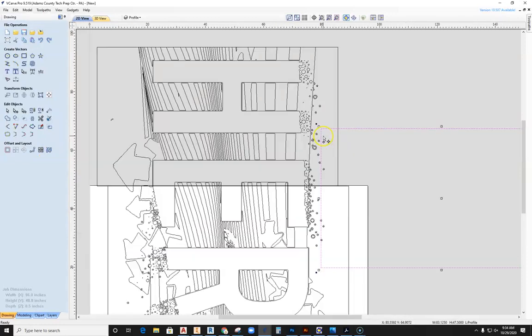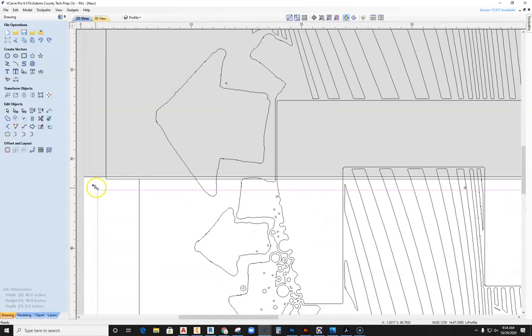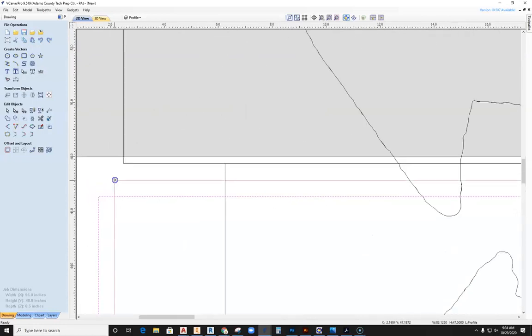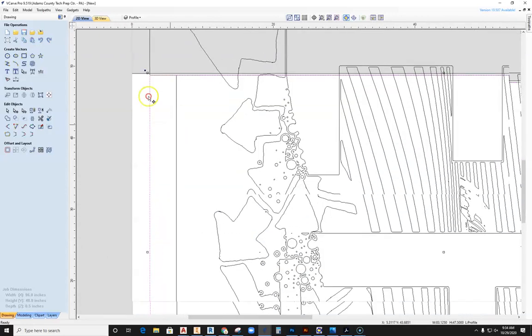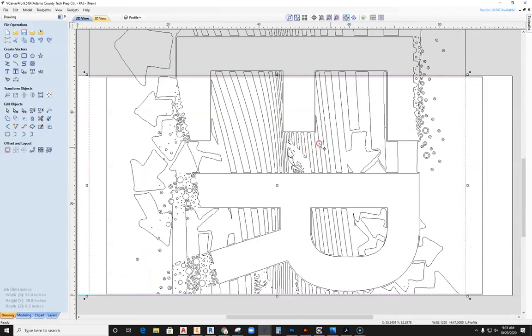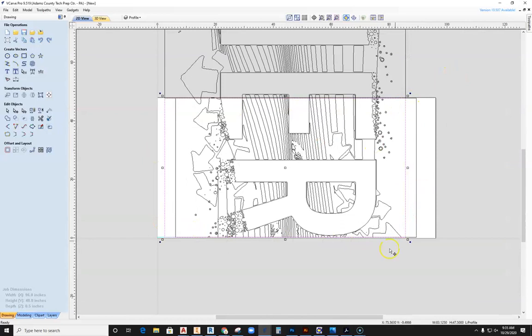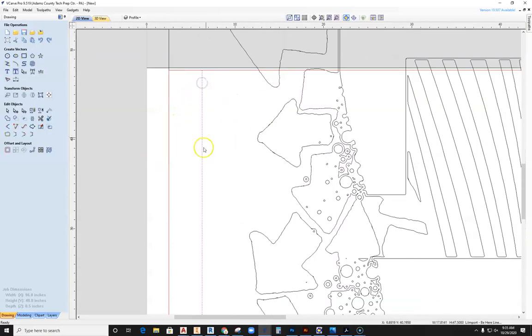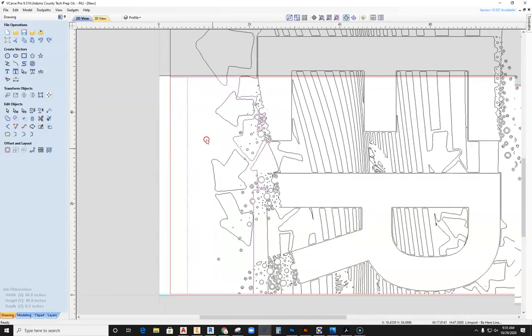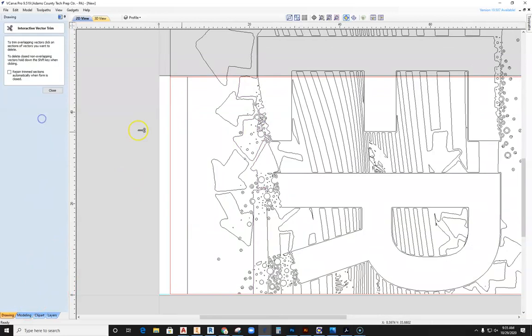That then allows me to take my rectangle and move it over to the old corner point for the mating sheet. This is going to become the new profile location for my new cut. Now I need to go in and start cleaning up the geometry. And that's where I start using my cut tool. So I'll go and grab my cut tool. I will cut this line out of here.